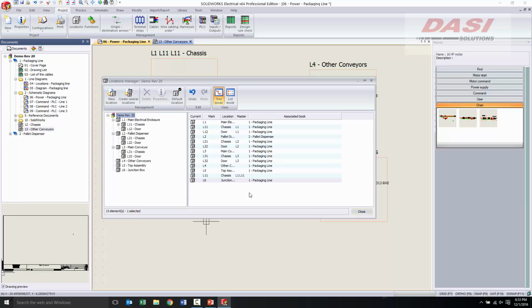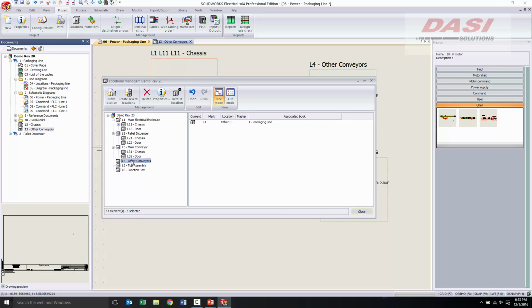But the big thing is, when you are selecting a component, where is the component going to be in the sub-assemblies? Is it going to be in one specific spot? Is it going to be on a conveyor and inside a cabinet somewhere? Is it going to be on a specific conveyor? Is it going to be in a specific field area? You designate where that's at, and that will help with the report if you're separating it out, or it will help when you're doing the plant layout or equipment layouts for where the footprint should show up.